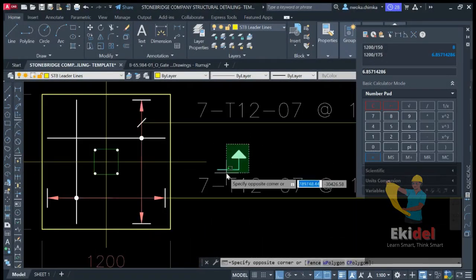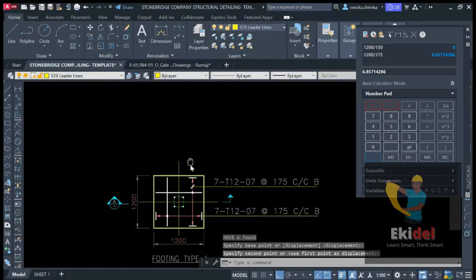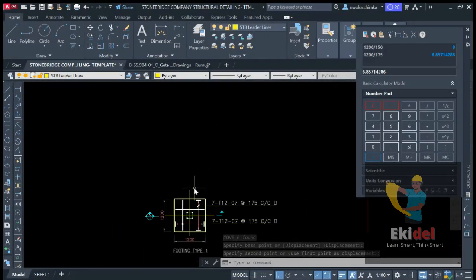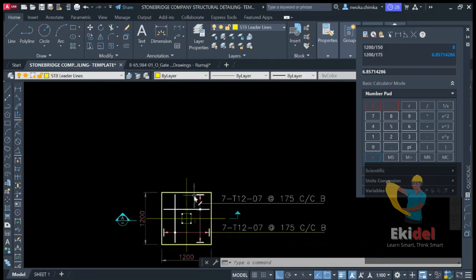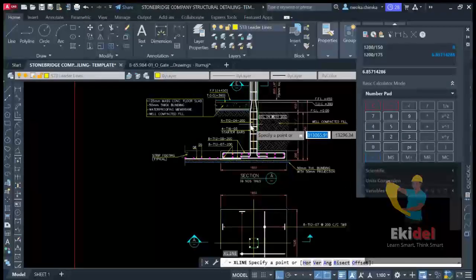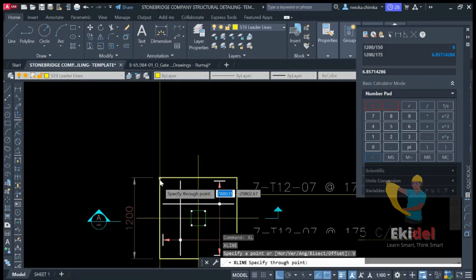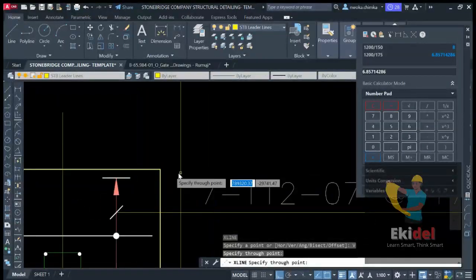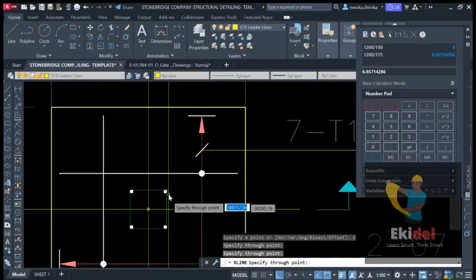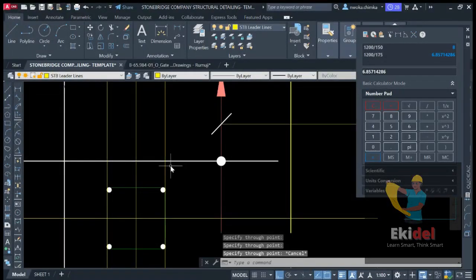But first of all, before we are done for this lesson for today, I'll just draw the section plan of how it will look like. Then in my next video, we will place the reinforcement for the section. Okay, so right now we'll just have to click on what? XL, enter. So we are applying this to draw this. So click XL, enter, V, enter, and put a line here, and then also trace this one out, and trace this out also, this column line, and also trace this out at this point. Now we will have to change this one color immediately because this is a column line.